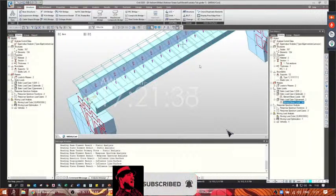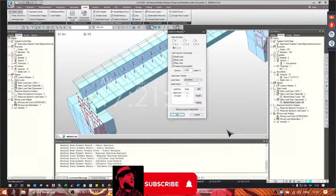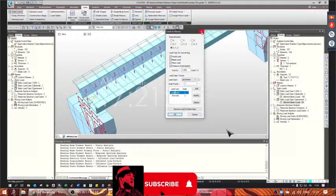These loads have been converted into masses through the function load to masses. Here we can see, okay, they are being added here. In this way, we can take into account these forces in the response spectrum analysis.